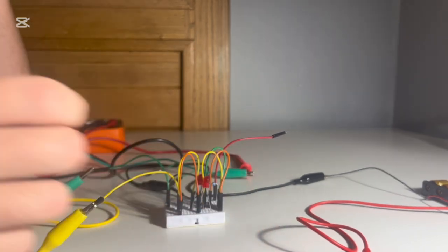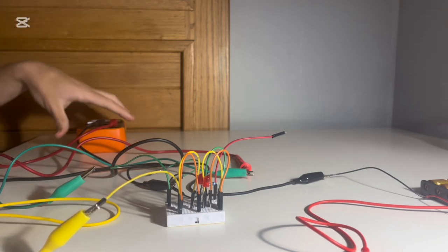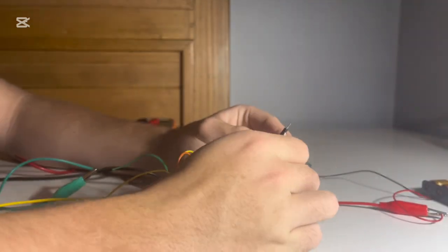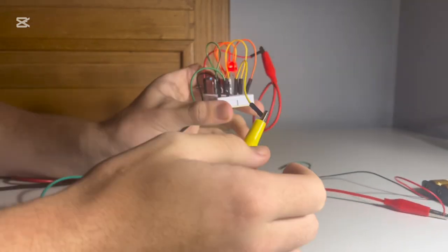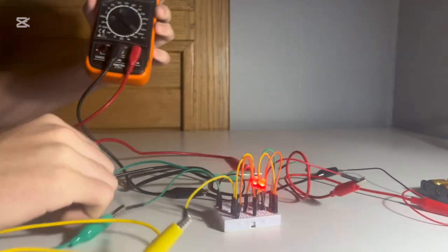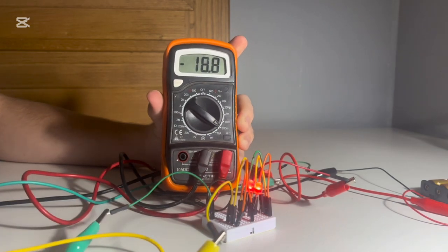Once repositioned, connect the power supply to the circuit and check the two LEDs light up to ensure the circuit is closed. You can see on the ammeter that the total current is 18.8 milliamps, close enough to our estimate. Current losses are probably due to wiring and the tiny resistance of the ammeter itself.